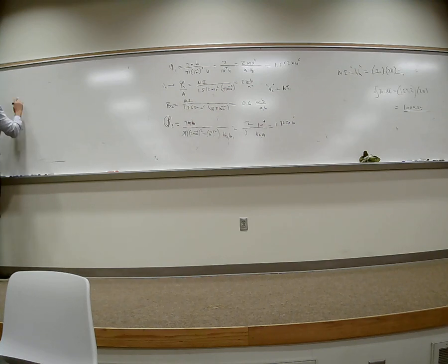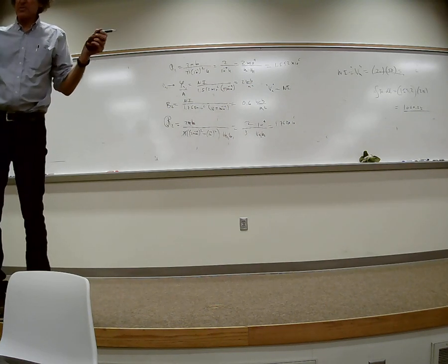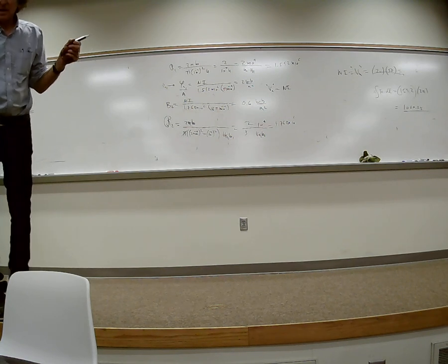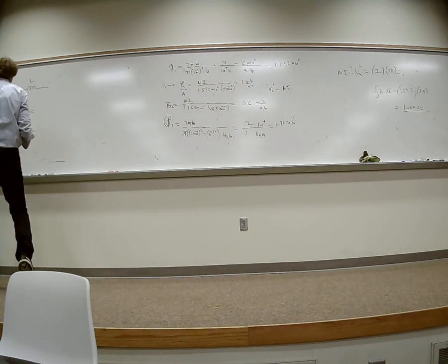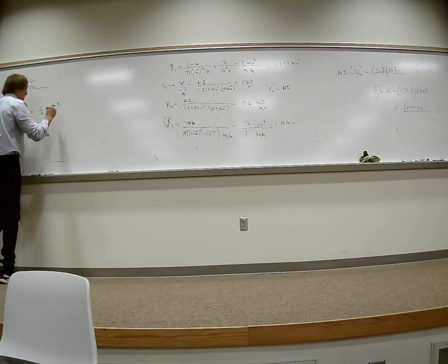So now, one thing to think about, if you just have your basic inductor, that's what our circuit would be equivalent to in terms of a lumped element that we just did. That's all it is. Well, if you have an inductor with a current I, what is the total energy? What is the magnetic energy in there? Total energy. How many remember? We could do 1/2 the integral of mu magnitude of H squared over the volume. We could do that. You all follow me? That would be the magnetic energy density integrated over the volume. But remember, when you have an inductor, the magnetic energy is what? 1/2 Li squared. How many remember that?